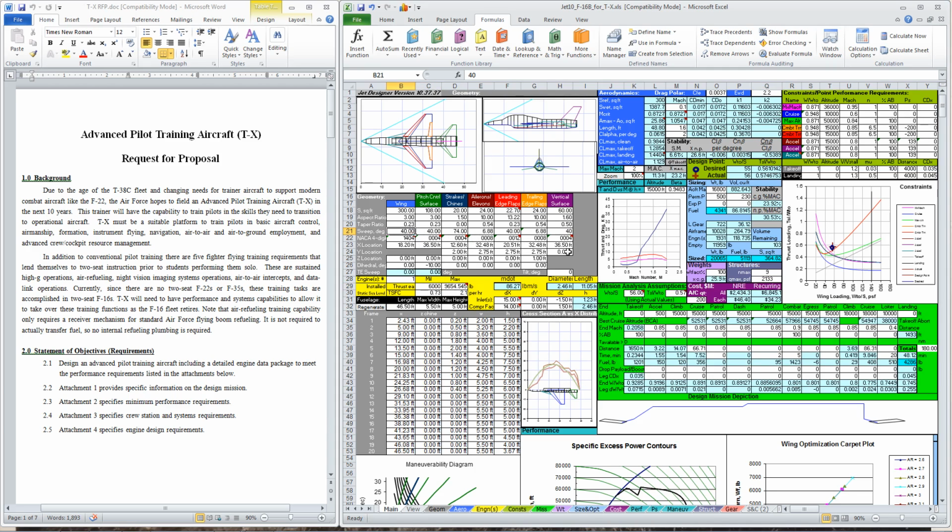Now the wing right now is swept 40 degrees, and that's primarily because the F-16 needs to go supersonic and needs to maneuver at 0.9 Mach, and that's what it was optimized for. And we can drop the design Mach for this mission because there's no requirement to go supersonic for this TX RFP.